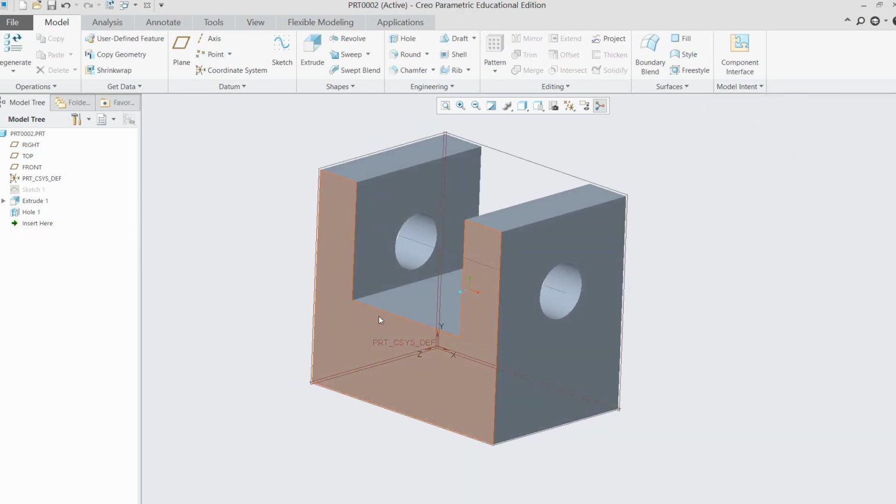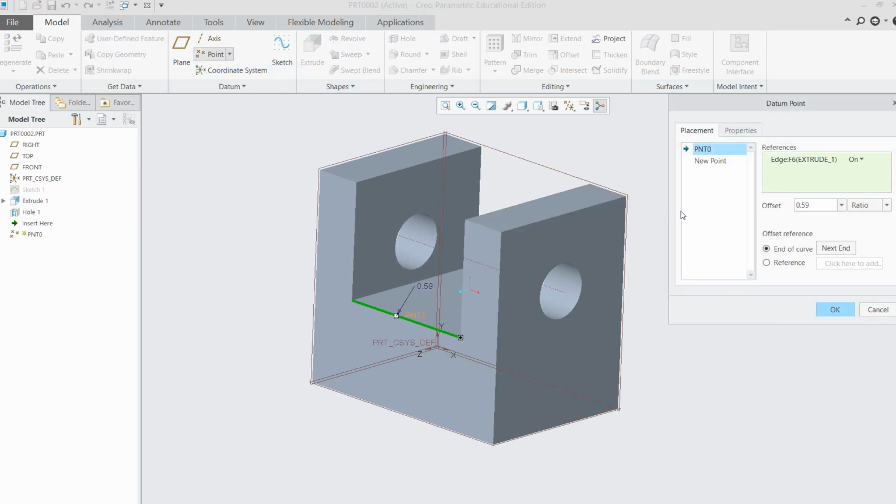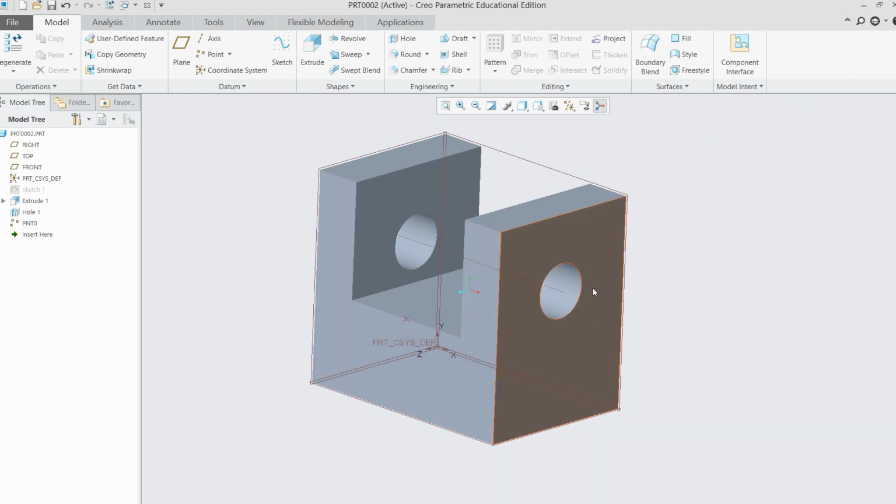First, on this edge I need to create a point. There are many ways of doing that. So that point is half, 0.5. It's parametric. So if you do 0.2, for example, it will take the location from the start point here to 0.2. If you put 0.9, it's around here. So halfway is offset 0.5. Okay, so I have that point.